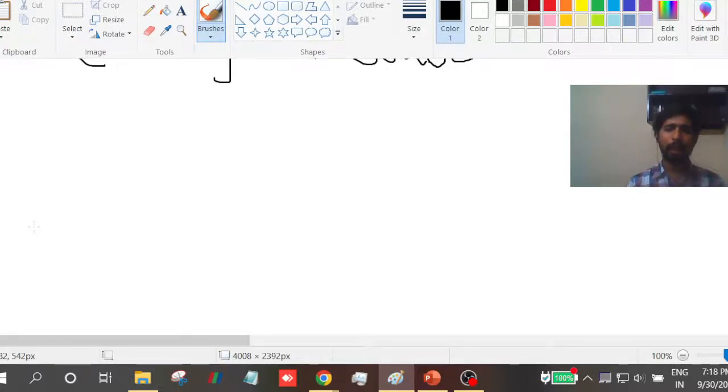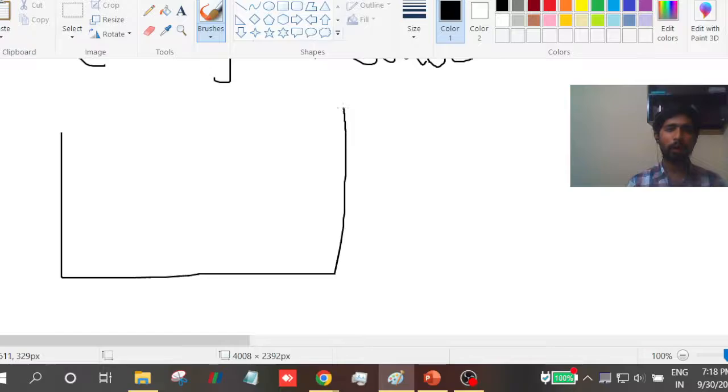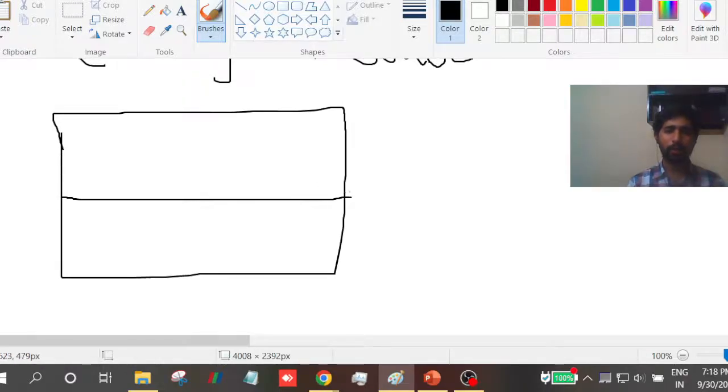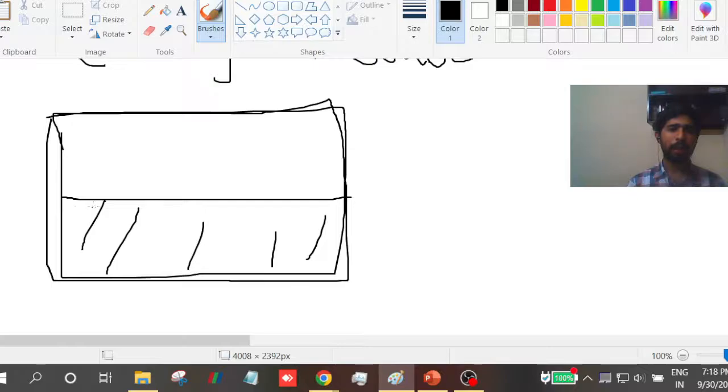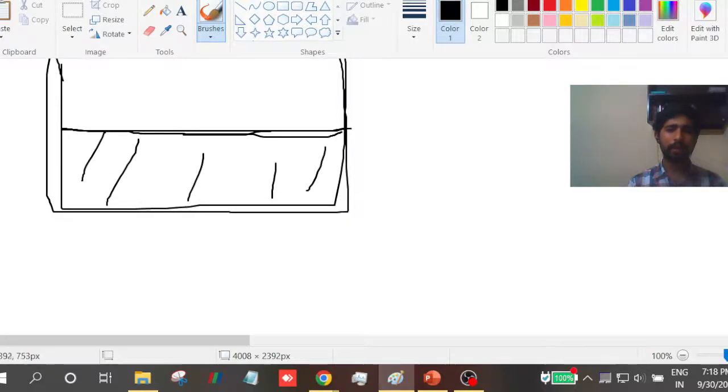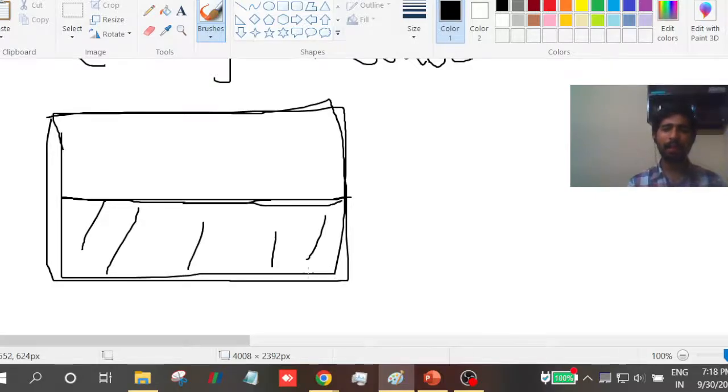Then you have something called the one fluid approach to solve the multiphase equations. What you do is, say I have water and oil in this particular tank, or say water and air also. I consider this whole body as only one fluid. And then after you cross this interface, I will just change the material parameters. I'll be solving the same Navier-Stokes equation only. This is very helpful, I would say, especially when you have liquids in your study. In those conditions, doing such studies will be really helpful, and it will reduce a lot of computational time also. You are solving only one set of governing equations in this one fluid approach.